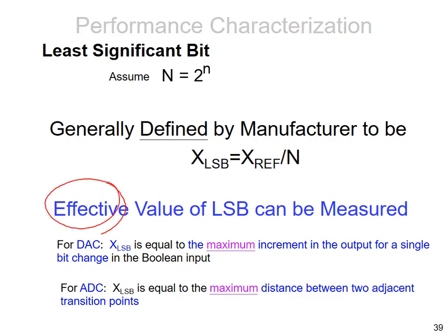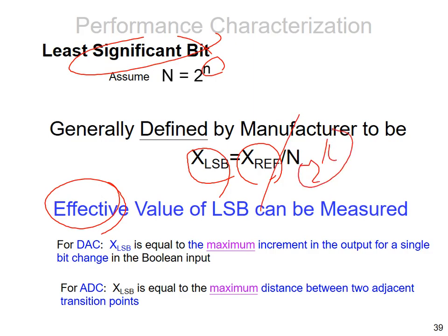That's it. So in theory, how large is your LSB? If you have n bits, right? If it is ideal, then 1 LSB means the operation range divided by the nth power of 2. Okay? That is in ideal. But sorry for that, I told you, after fabrication, each step will be different, totally different from the others. So, for effective LSB, we measure the largest. Got it?